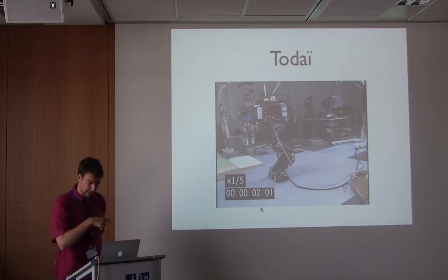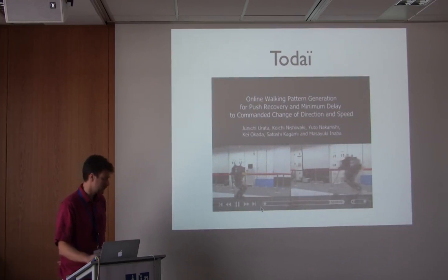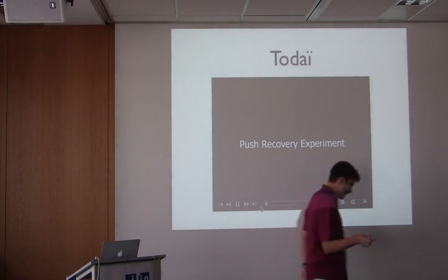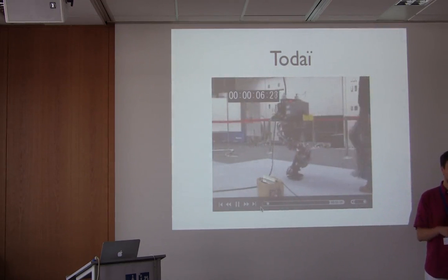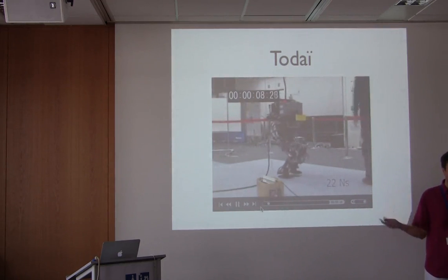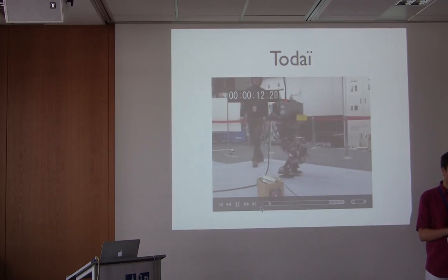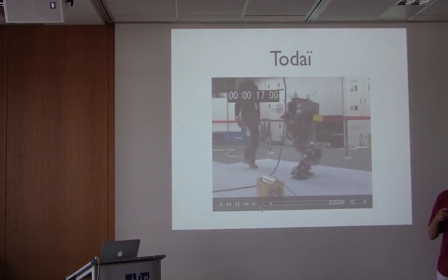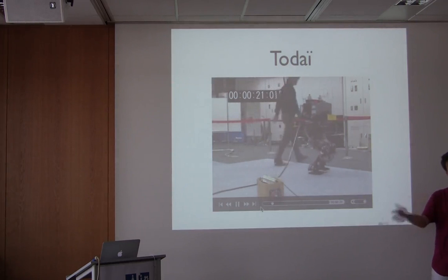I speak a little bit in the paper about some very important results obtained recently, about deciding what's the best option to react to a perturbation. First idea, you can use angular momentum, and then it was shown that it doesn't help that much. What's more effective is doing footsteps, adaptive footsteps. But then you have two potential variables: one is the length, and one is the speed.